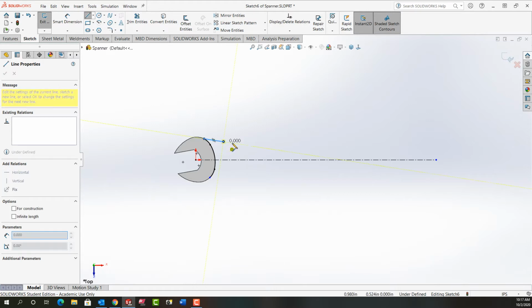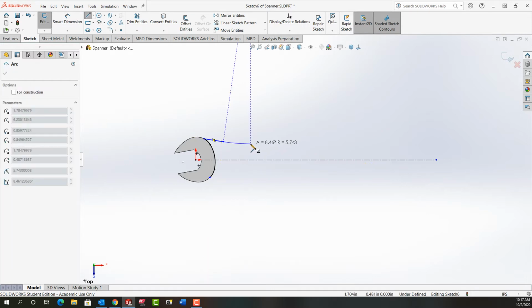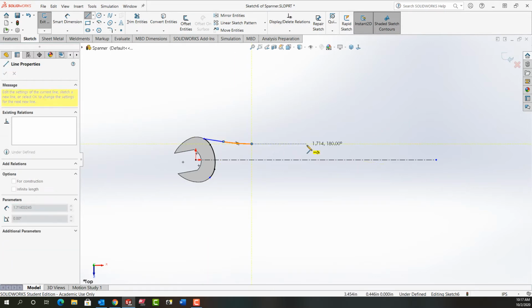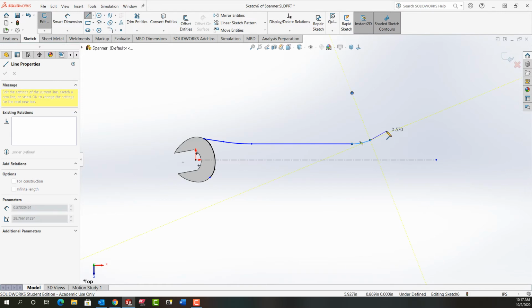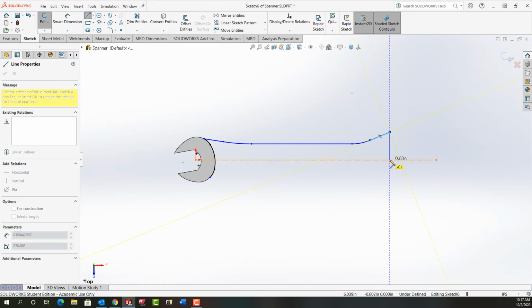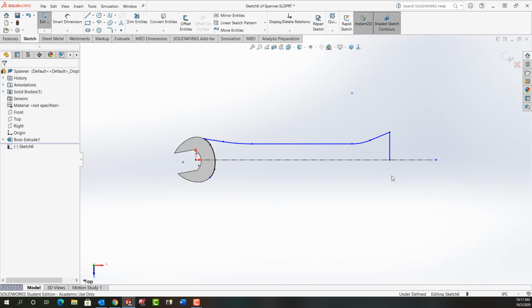And then I want to switch into arc mode. So I can push A on my keyboard, or I can just move off and back over that arc, and I'm in arc mode. I'll click to create it. Back into line. Again, I want arc, move off, back over, create this arc, get my tangent line, and then I'll come down here, and I'll lock it.